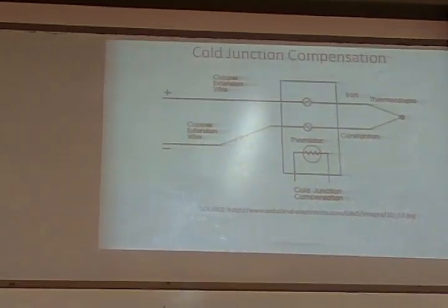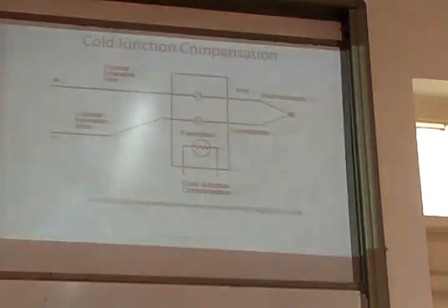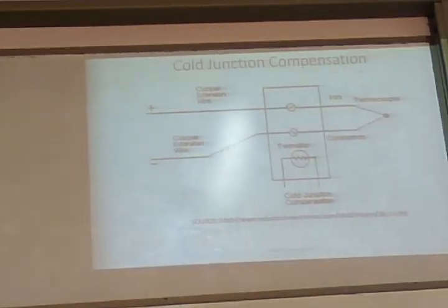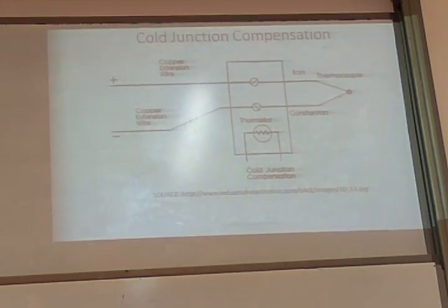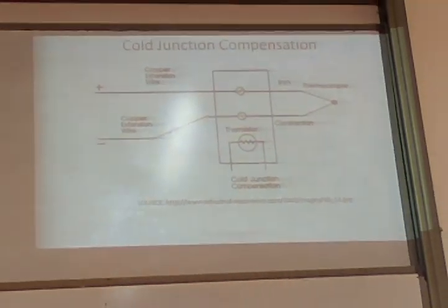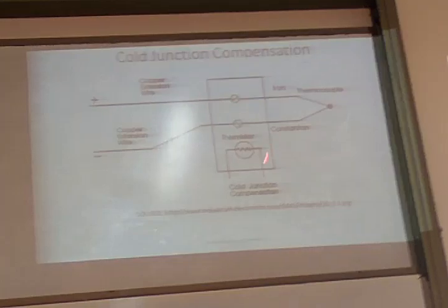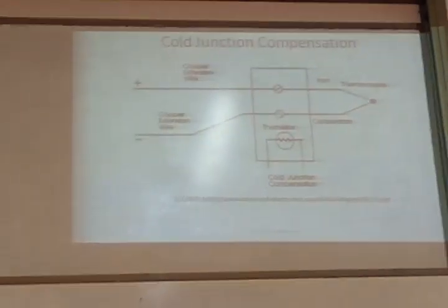That is the range of temperature for the most commonly available thermistor and RTD material. A thermocouple can measure up to 1000-1500 degrees Celsius. When you want to measure higher temperatures, you have to depend on a thermocouple. So you don't mind spending a little extra money to measure the cold junction, so that I don't have to carry the ice bag along with me, but still I will be able to measure. So I know the cold junction temperature, I know the voltage that is developed, and I can find out the hot junction temperature.